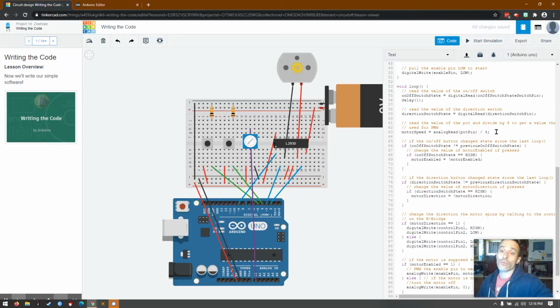Now, pulse-width modulation is the way a digital output can act like an analog output. So it sends variations of on-off depending on what we choose for that pulse-width modulation. So it's turning on and off at a certain rate, and that'll make things either go faster or slower or be brighter or dimmer, or it seems almost like it's more voltage or less voltage.